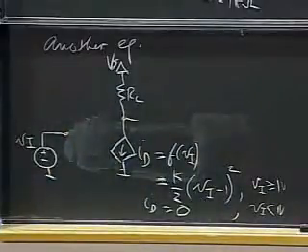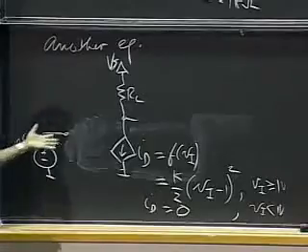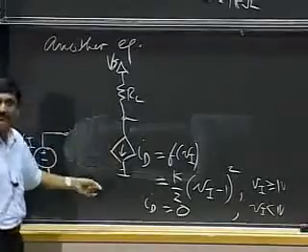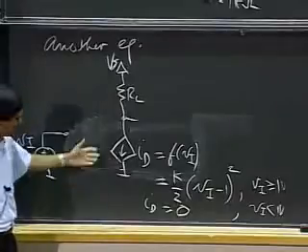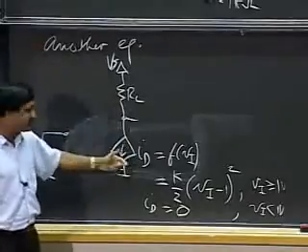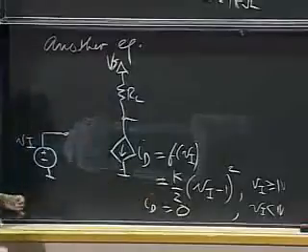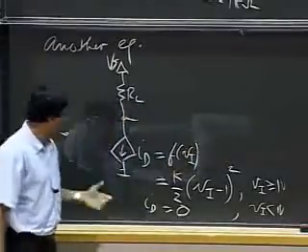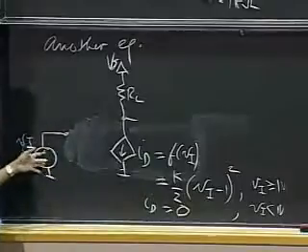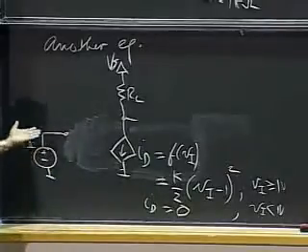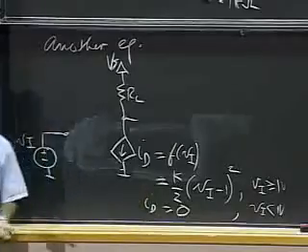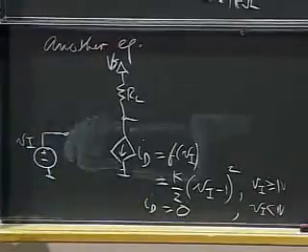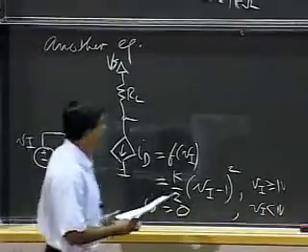Okay, but it's a dependent source, and it can have various forms of dependencies on the input. I just picked an example of some hypothetical, or as yet hypothetical, dependent source, the current through which is related to the input using a square law relation, (VI minus 1) whole squared, as long as VI is greater than 1. And if VI is less than 1, then the current is simply 0. It shuts off.